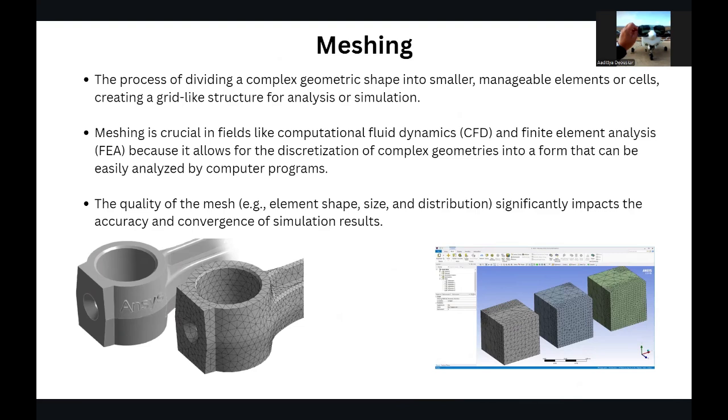You have to note that there is a limit on how fine a mesh can become because of computational requirements. The finer the mesh is, the more computationally demanding the simulation is going to be. So it depends from computer system to computer system how fine a mesh you can simulate your flow into. This is what basically affects the accuracy of your simulation.